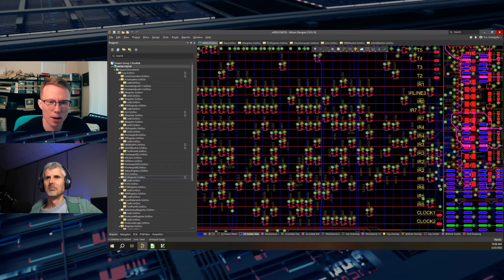So I used 100 ohm resistors, loaded the no-op instruction, and just had it fetch and execute. Of course, it fetches the reset vector address first, and it's just going to get the no-op instruction, which is fine. That's your initial program counter, and then the program counter will simply increment, and that's what I was looking for.